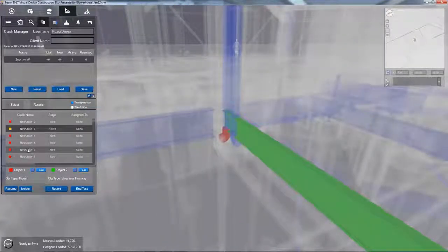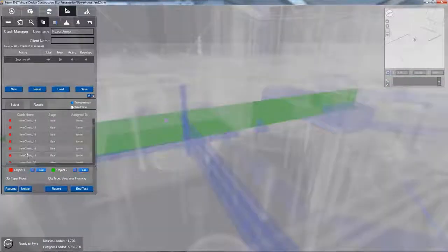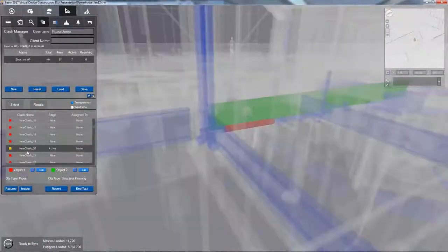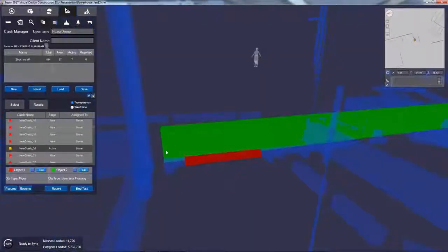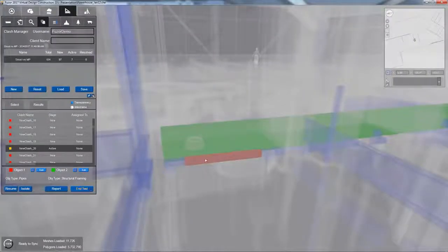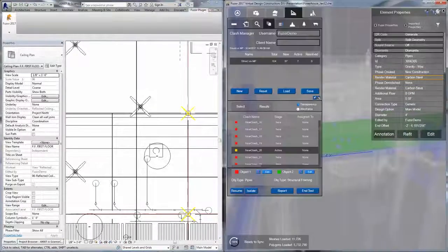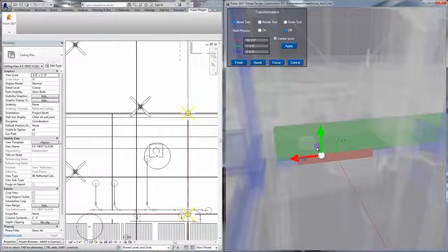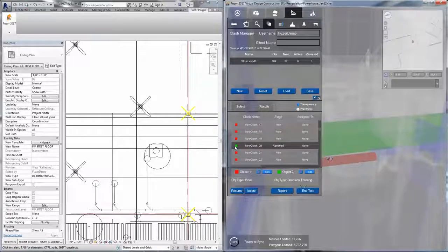So let's say, for instance, this is kind of the reason I live linked back in there. Let's say I'm looking at clash number 20. Well, I can see that I've got my highlights on. If I isolate it, I can see where that is. I've got a complete run going over here. So let's say I have purview over that movement. What I can do is say refit, and I'm just going to do this manually right now rather than giving an exact number. But let's say I shift that over, what I'm going to notice is in my clash detection here, it's going to show me green.